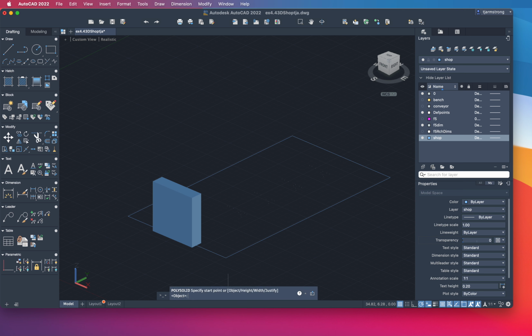And then there's something called justify. Let's type this first, justify. And this specifies whether the wall that we create goes to the right, left, or on top of this line that we create. And we want this to be right justified, which was the default as before.